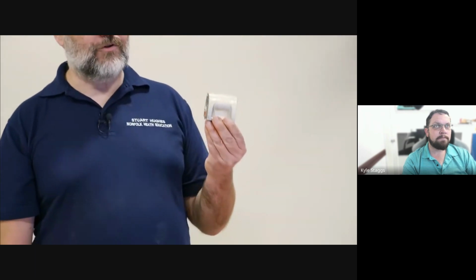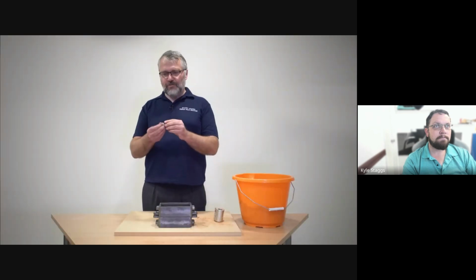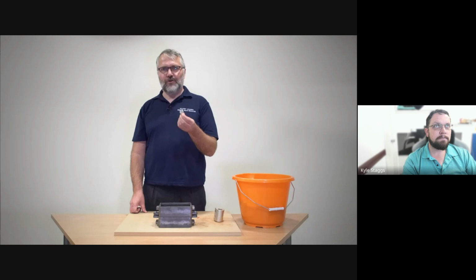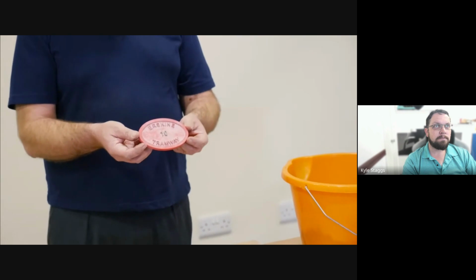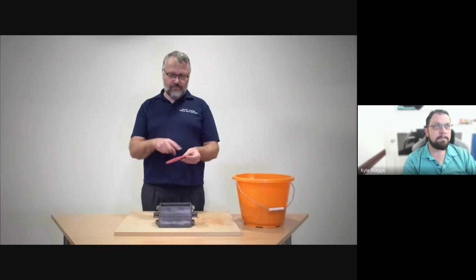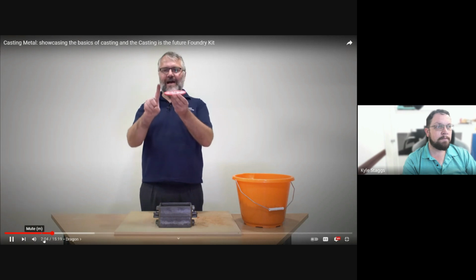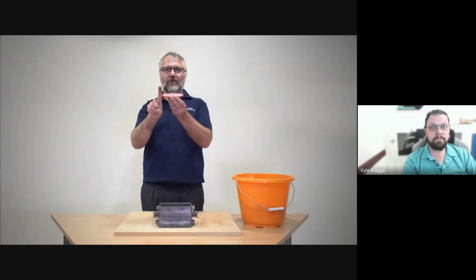Today we're going to make two products. The first one is a small cylinder or bearing block, and we'll use sand moulding to produce that. The second product is a small coin, a supermarket trolley token, so that you don't have to leave your pound at the supermarket. To make a simple object, such as this little number plate, it's quite easy to just make it as a one-part pattern which can easily be produced and removed from the sand. It does have sloping sides, it has the draft angle, just like the slope on your sandcastle bucket.